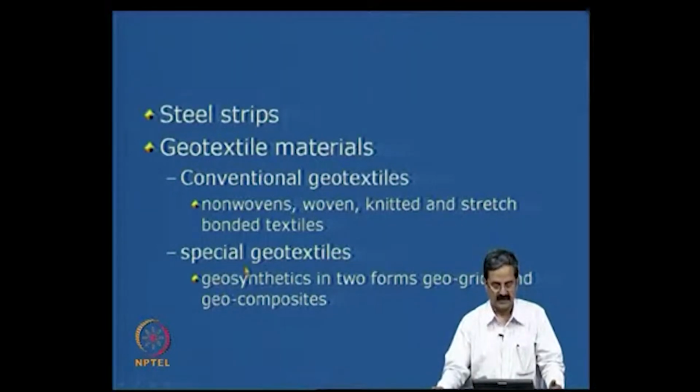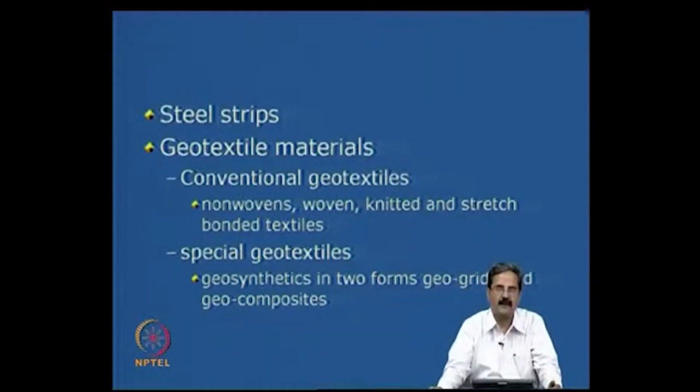Sometimes even special geotextiles, like for example geocomposites, are used. As I said, when the pore pressures are going to be higher or if the clay is somewhat poor quality, we can use a geocomposite in which you have a reinforcement as well as a drainage material attached to it. So the reinforcement is good enough to take care of the lateral pressures, and the drainage action of the geocomposite helps in draining the backfill.